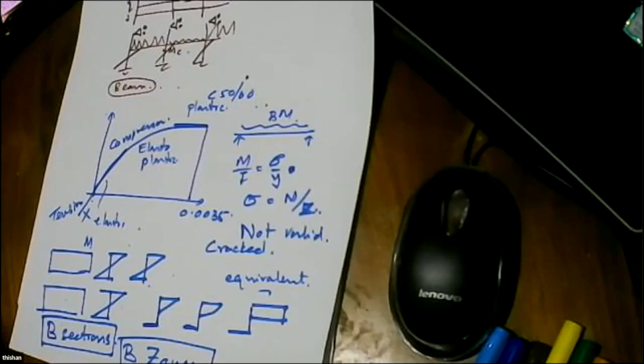Knowing that in Sri Lanka we have BG 24, 28, 30 big German machines that can easily break into rock, we decided to do something different: we are going to socket more. In our tender document, we had 6 meter socketing, 7 meter socketing, 5 meter socketing.